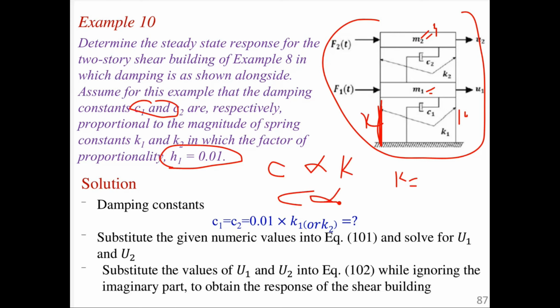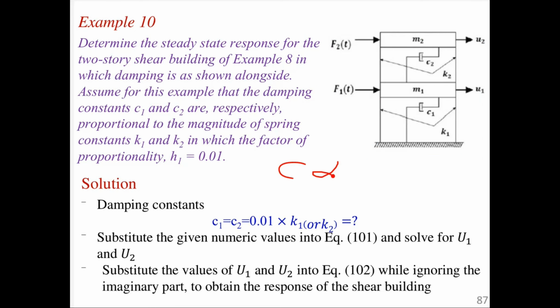If we take the modulus to represent a material component, then you are saying C is proportional to Young's modulus. Again, we know that the stiffness is proportional to Young's modulus, Poisson's ratio, and things like moment of inertia to represent geometry. So both of them are related to the material, one because of viscous damping, the other as a result of the stiffness. But the magnitude, of course, will not be the same. So this is maybe 0.01 E, and this is maybe 1 or something like that.